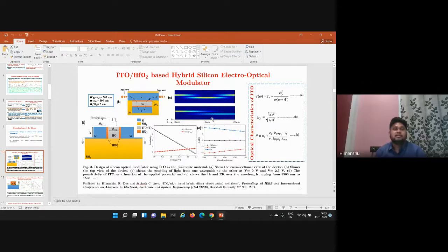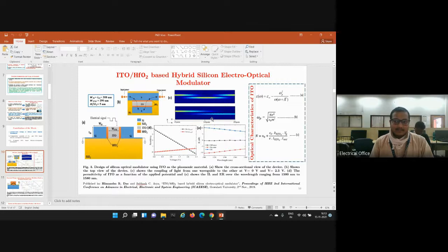So actually, extinction ratio relates to the switching speed. Switching speed depends on the switching from on state to off state. Here we have calculated the losses at on state and off state, and from there we are calculating the extinction ratio. So the higher the value of extinction ratio, the higher the switching speed. Yes, so this is better performance. So these are the minimum extinction ratio you are going to offer, right? It can be higher than this, yes, sir, it can be higher. This is the lowest configuration you are offering, but when you actually design this modulator, it can work at a very high value, right? Yes. So this was my first query regarding your first work.